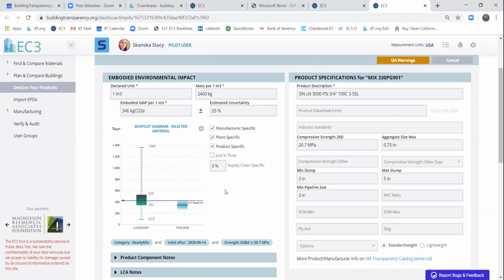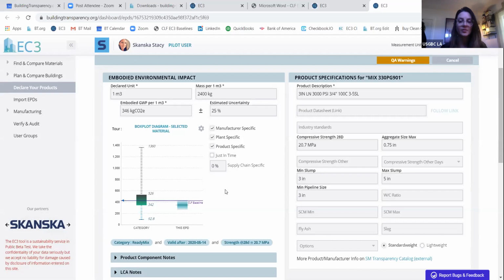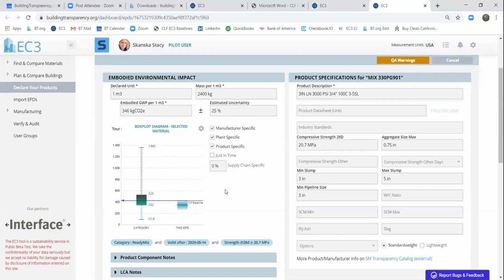So we do not even include end of life. A1 to A3 for embodied carbon is the extraction emissions, the transportation emissions to a manufacturer, and the manufacturing emissions, so cradle to gate. And that's for 2 reasons. First, because that is, again, where the largest impacts are. And second, because just like the next phases, the use phase and then the waste phase, those things can vary greatly from owner to owner or project to project, based on a churn cycle for updating carpet tiles, or what might happen in the waste stream in 50 years.